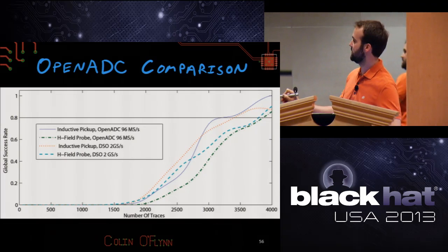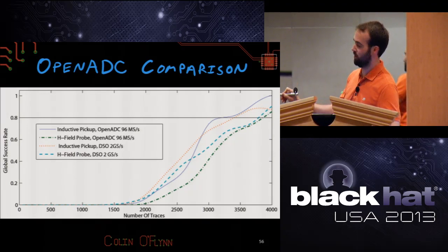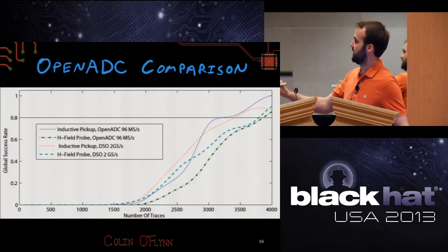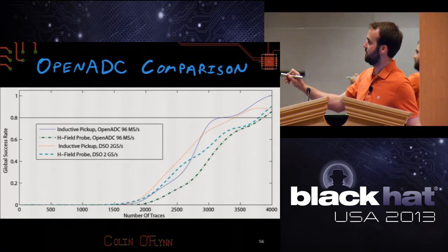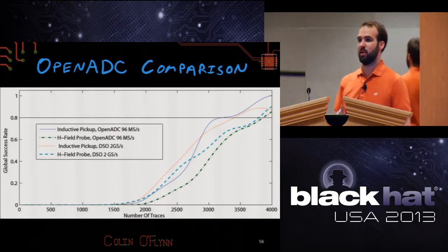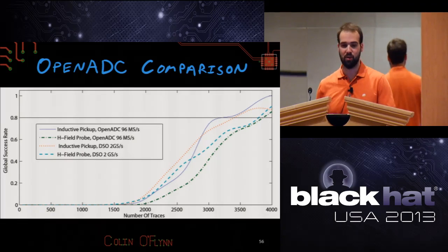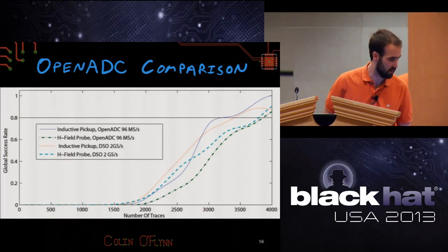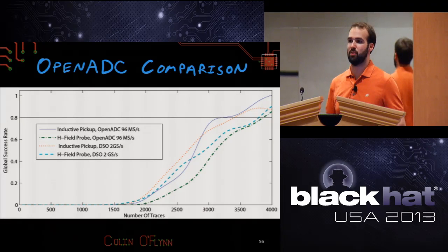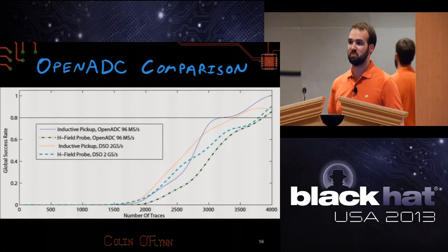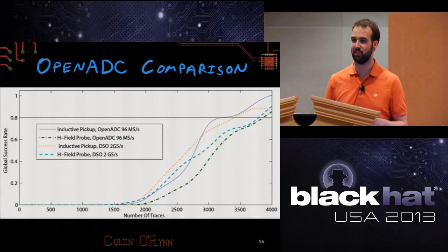It takes more traces, so here it's taking 3,000 traces, and there's a different metric plotted here. This is the success rate. So I'm saying if I measure the power 3,000 times, 80% of the time I can recover the exact correct key in this hardware implementation, even though it's doing everything at once. So it does in the end work out. Make sense? Other questions? Yep.